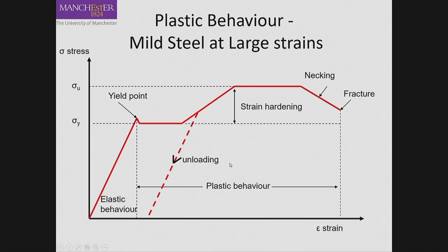And this graph shows the main reason why we use that for fishing rods. When you unload, you basically got yourself a new elastic graph. Yep. You technically got yourself a new apparent yield stress. Absolutely. This is why people pre-stretch fishing rods before selling. That's good, but I'll try to get you for that example, paper clip or something.